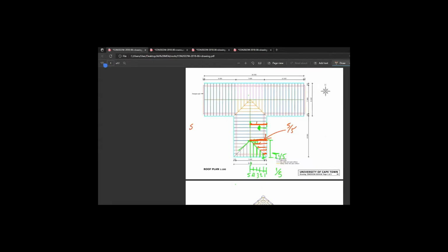Okay, first category, not exceeding 2.4. So what's happened here is you've taken your 5743, which is given, and you're going to apply intervals of 1/5. So let's go across. 5743 divided by 5 gives you x. X is this smallest multiplier. And all you do is go 1 times the smallest multiplier, gives you that one. 2 times the smallest multiplier, gives you that one. 3 times the smallest multiplier, that one. 4 times the smallest multiplier, that one. Done. Easy peasy. 5 times 5, we ignore. Well, we don't ignore it. It doesn't apply, because it's no longer jack rafter. So that is those ones covered.